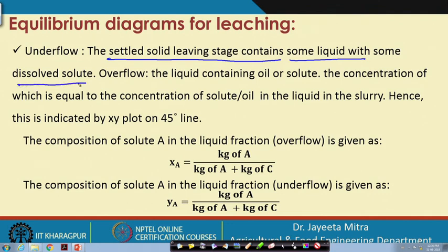That associated liquid is called the underflow, and that liquid will have some dissolved solute as well. Overflow is the liquid containing the oil, or the solute that is being extracted. That has been taken away in the overflow, right. Its concentration is equal to the concentration of the solute in the liquid in the slurry. So these two concentrations, the concentration of the solute in the overflow and the concentration of the solute in the solvent going with the underflow, will be the same.